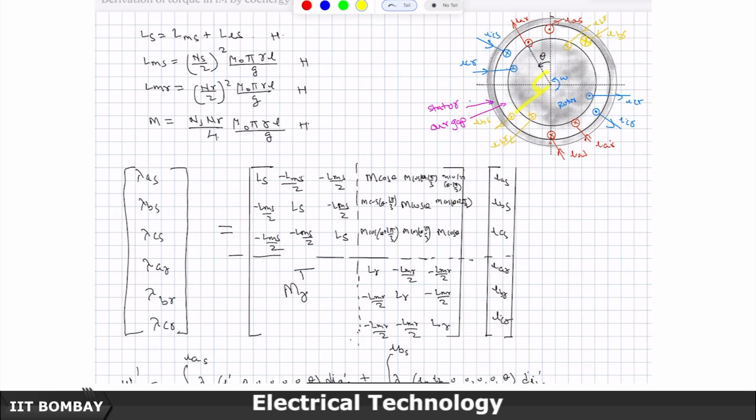So, this angle is 120 degrees, and then since the rotor has moved by theta, just like between A of stator and A of rotor the angle is theta, similarly between B of stator and the corresponding conductor B of rotor, an angle of theta has happened. So, between B of stator and A of stator 120 degrees, additional theta here. So, it became 120 plus theta.